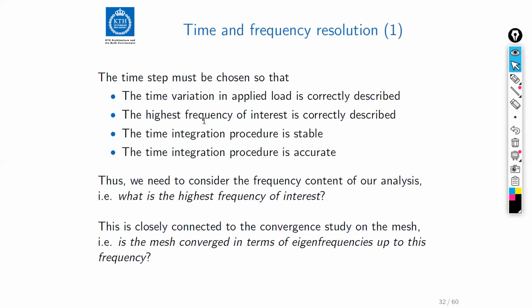So actually, if we do a time domain analysis, it might occur that we think in our heads that we are considering the first 5 modes, but in reality, since this is in the sense of time a continuous function, if we use time domain methods to solve the equations of motion, we will include all the frequencies that our discretized time can represent. So we might need to actually filter the results in the end, if we are actually limiting ourselves to a certain frequency range.